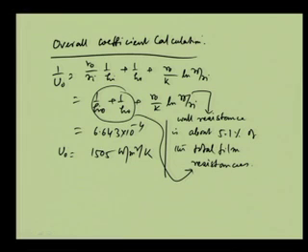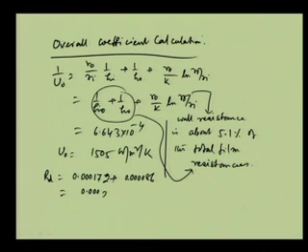Now, what you have to find out is RD. For two different fluids, we will take RD as 0.000172 for one side fluid plus 0.000088 for the other side fluid. So, this total becomes 0.000258 meter square Kelvin per watt. One side fluid is water and the other is benzene. Okay. So, we will take something like that.